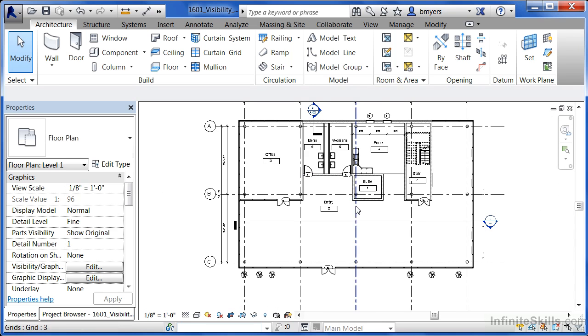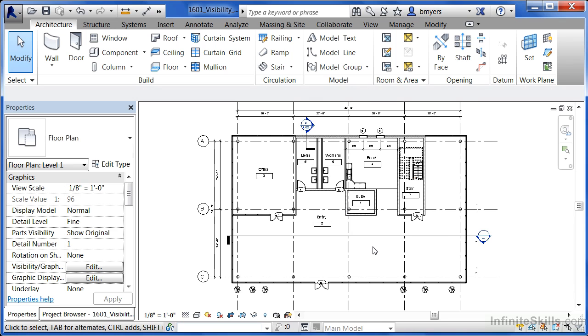Certain objects in Revit can actually have the colors of blue and green and red. You can give it any color that you want. So these do not have to be limited to being just the color of black like we've seen up to this point. Visibility graphics can assign those colors as well.